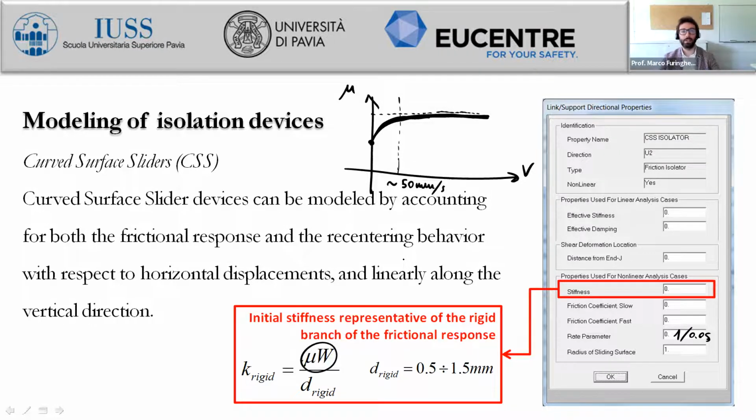We have seen yesterday the huge, exponential decrease in trend of the friction coefficient with respect to the applied load. And that is much more significant with respect to the slight increasing trend of the friction coefficient with respect to the sliding velocity.